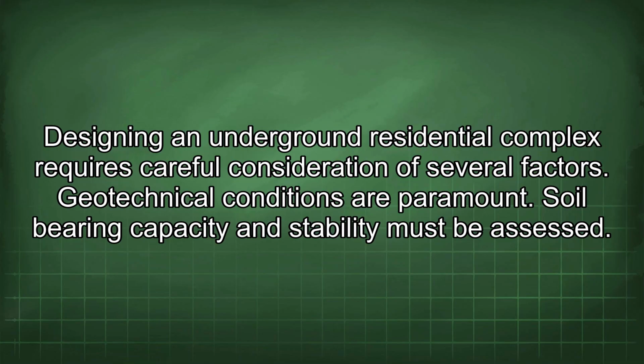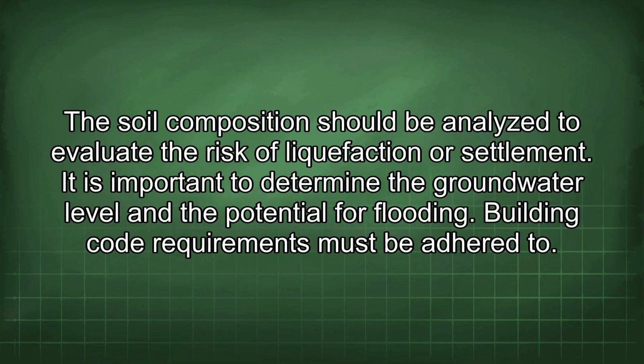Designing an underground residential complex requires careful consideration of several factors. Geotechnical conditions are paramount. Soil-bearing capacity and stability must be assessed. The soil composition should be analyzed to evaluate the risk of liquefaction or settlement. It is important to determine the groundwater level and the potential for flooding.